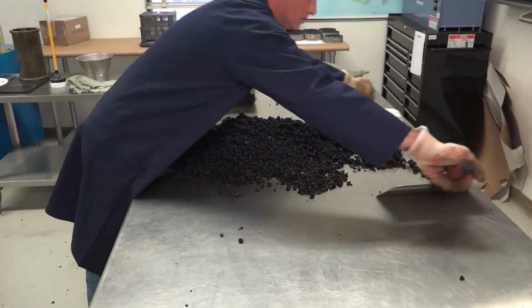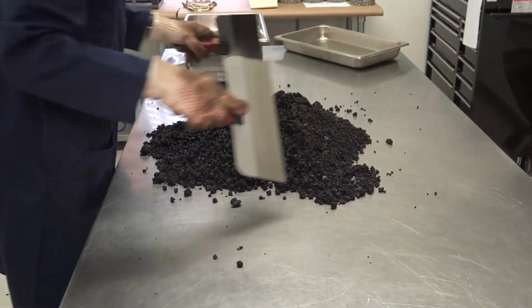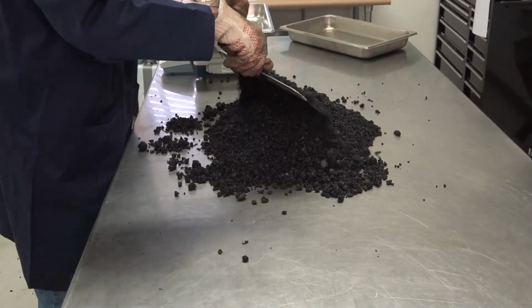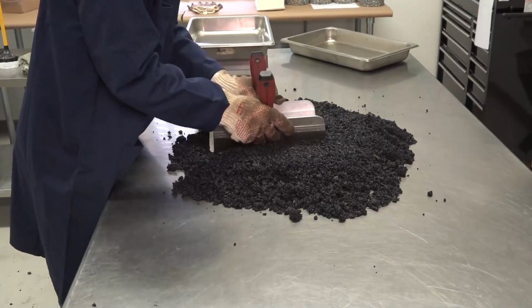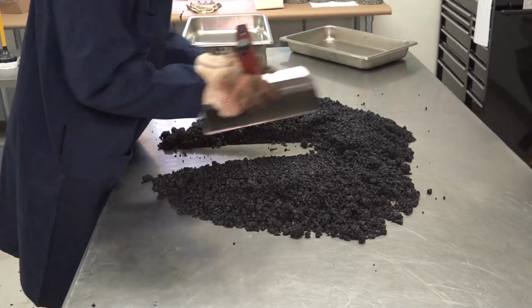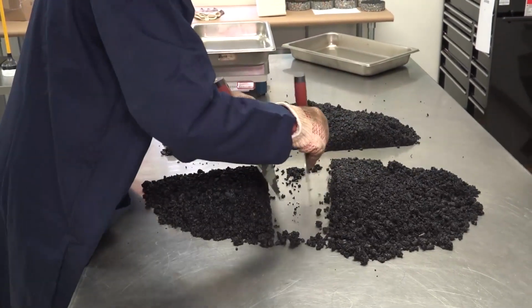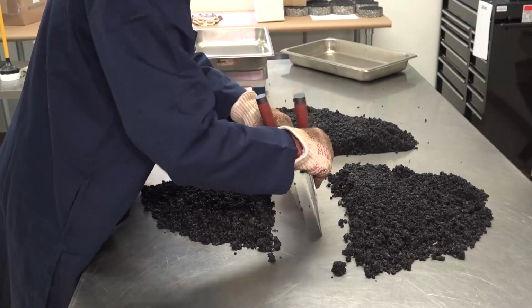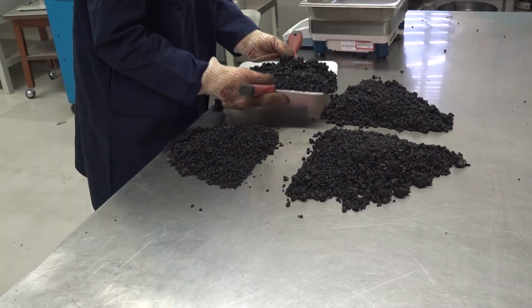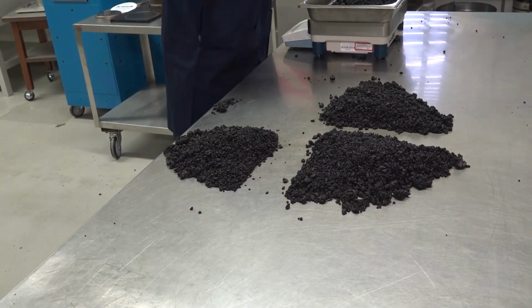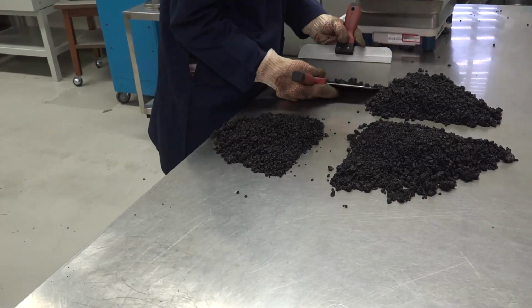Plant-produced asphalt mixtures should be evaluated to make sure short-term conditioning has taken place during production and delivery. For short-term conditioning, refer to AASHTO R30, Standard Practice for Laboratory Conditioning of Asphalt Mixtures, and DOTD, Applications for Quality Assurance Specifications for Asphalt Concrete Mixtures.